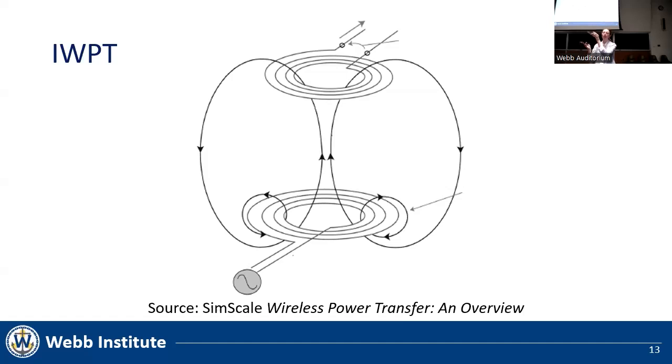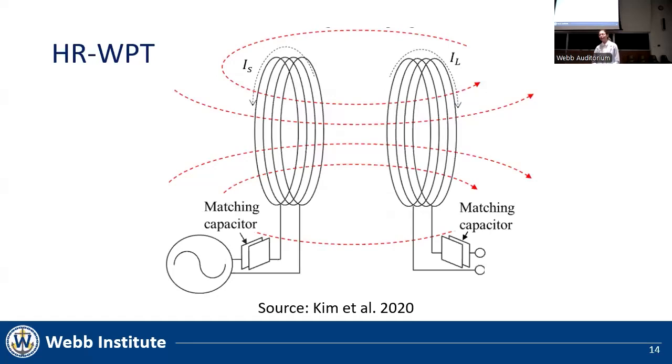induced current. The problem with using IWPT is that it is a near field technology. It is very effective over small distances, thus it is tightly coupled. However, if I move the device away from the source, even by a small amount, little to no energy will transfer. The same goes for changing the orientation of the coils. And all of these inefficiencies are happening in air, which completely changes the game when seawater is involved. This is where highly resonant wireless power transfer comes in.